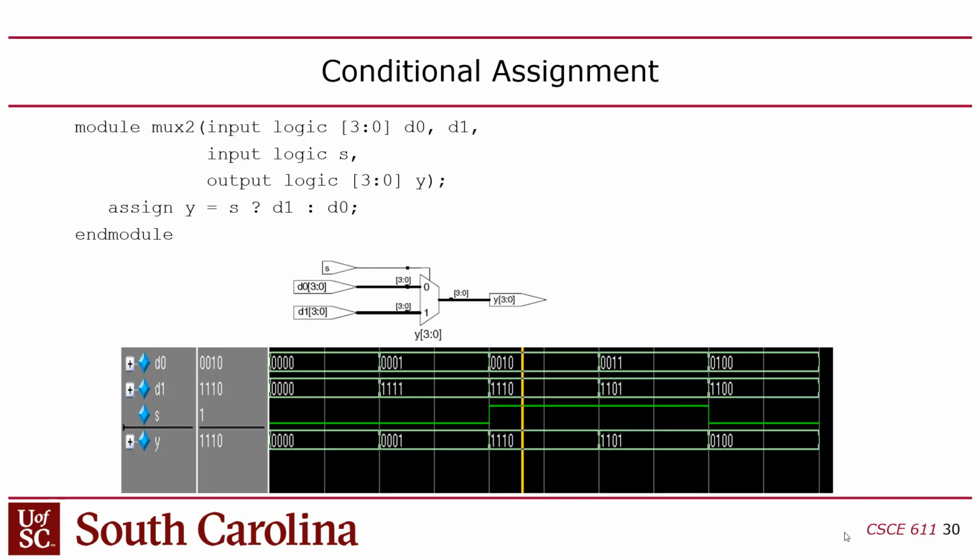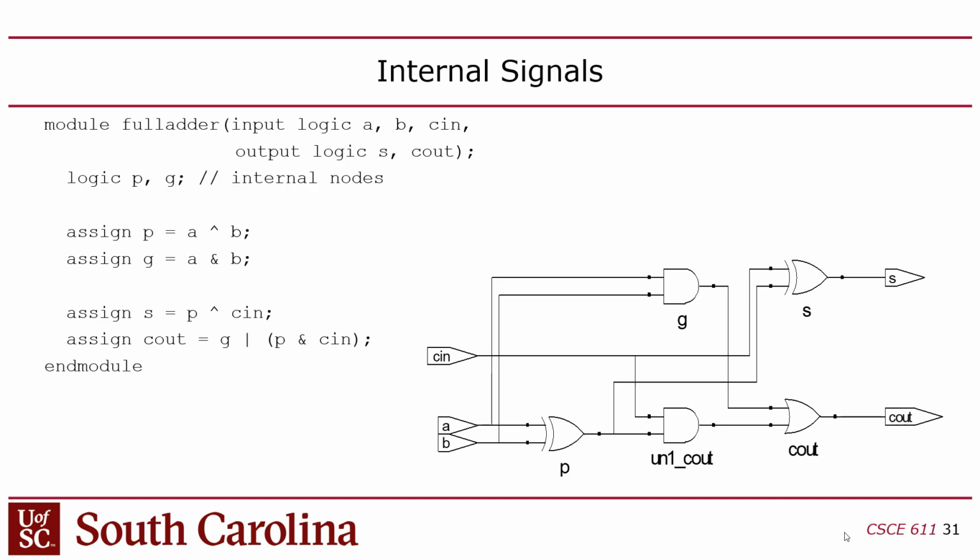So in this case, I have a 2-to-1 mux where the inputs and outputs are 4 bits. Now, by the way, it's very unlikely that you'll ever build a mux in its own module. You can do that, and that's what we did here, but it's more common to take this single line of code that creates a mux behavior and put it inline in structural code. That's typically how it's done. So this is a way that you can quickly deploy muxes, or if you want to create a module for it, you can, but it seems like a lot of effort to just wrap that one line of code up. All right, so then I already showed you this too.